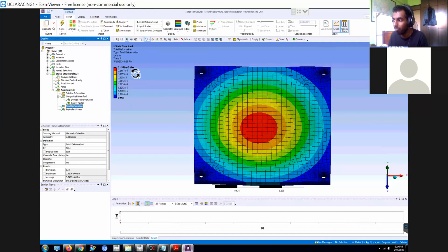The only issue comes in when you're doing something with like a seat, and you find the plies going up to like 12, 15, 18 plies. Then that's where the issues tend to come in, because number one, you also need to consider that you are going to be putting down each of these plies, and anything above 8 plies can get very tiring and very time consuming.